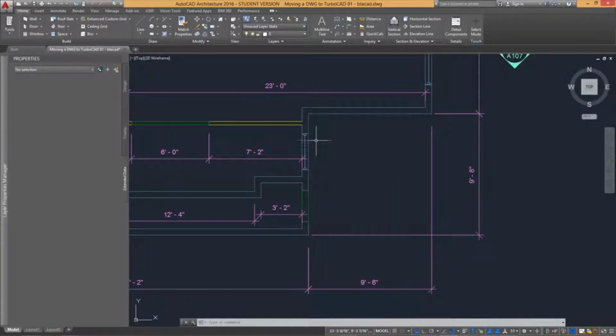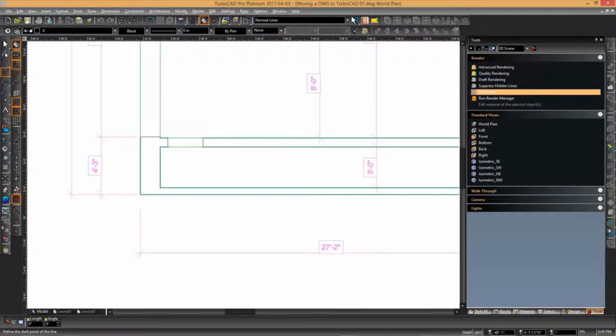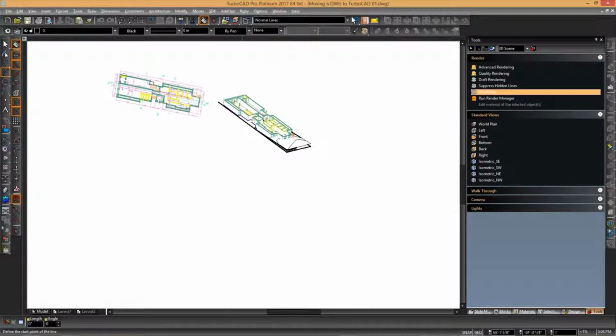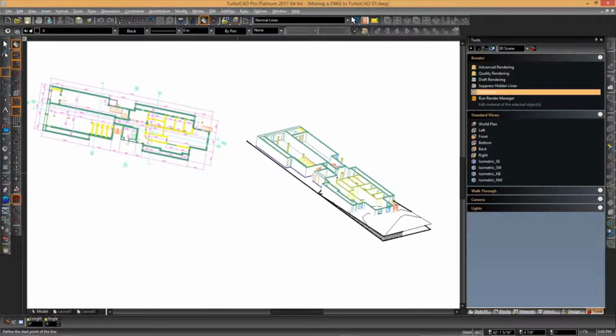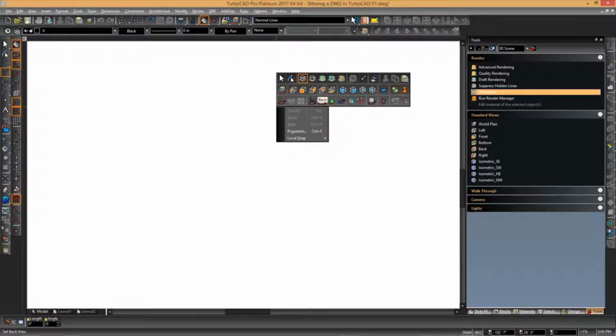The default TurboCAD interface, however, is set up to invoke the 3D Examine mode by clicking and holding the wheel mouse. This is often confusing to AutoCAD users who are familiar with the dragging of the mouse button in order to pan. New users who are unfamiliar with this Examine tool also think that their drawing has been corrupted and it is now at an angle. In order to return it to the top view, you can simply right-click and choose the World Plan option.